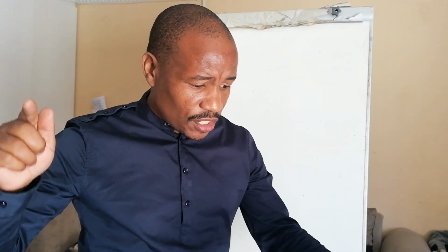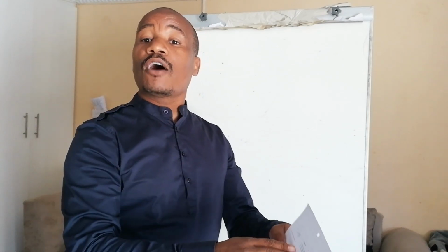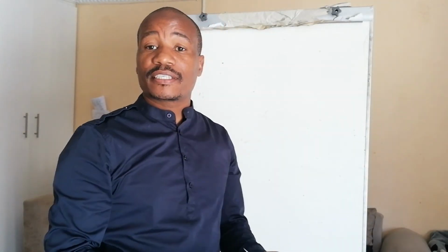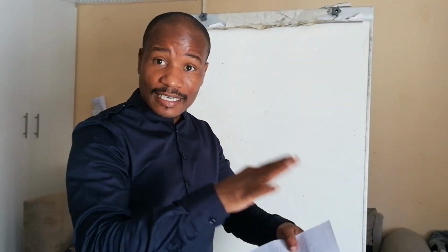If they want to give you an input, they will tell you an input to the motor. But if it says 100 kilowatts, 3,300 volts, 50 hertz, three-phase star-connected, it is the output. This is the information on the nameplate of that particular induction motor. These are the rated values of that particular motor.